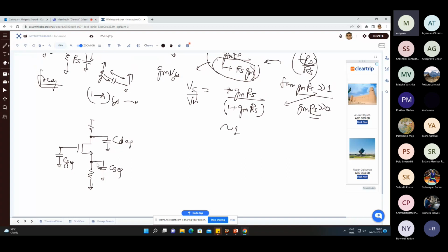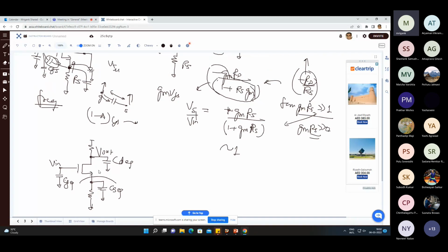Now still, in order to find the input signal swing from Vin to Vout as an expression of these three capacitances, if I say that this capacitance is negligible, then it is easy. Then it is just like your common source amplifier, where you have taken care of the Miller effect. The justification may be valid because we are talking about ignoring CSB.